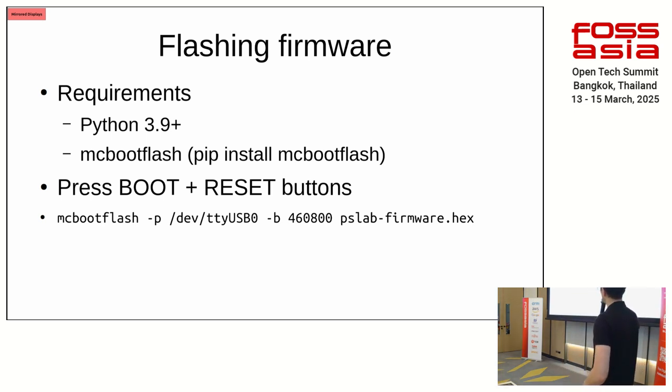Flashing requires Python. That's why Python is required for the firmware development too. There is a tool called mcbootflash, which you can install with pip install. And then you need to put the PSLab into bootloader mode.